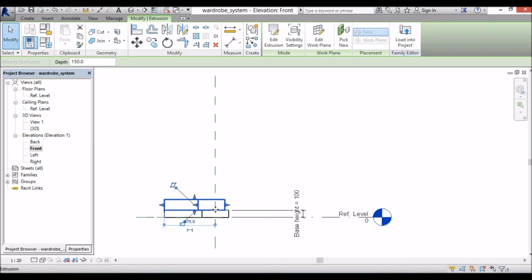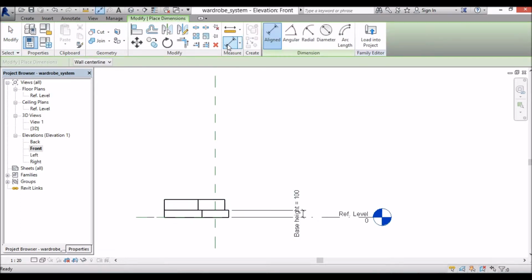So I'm happy now that I've positioned that floor where I want it to be, which is on top of the base. The floor doesn't sit underneath the base. Now, we want the height parameter to be applied to the floor here. So again, we put a dimension on that floor up here in the Align Dimensions tool. And we click on the bottom of the floor and we click on the top of the floor and we can bring that out there.